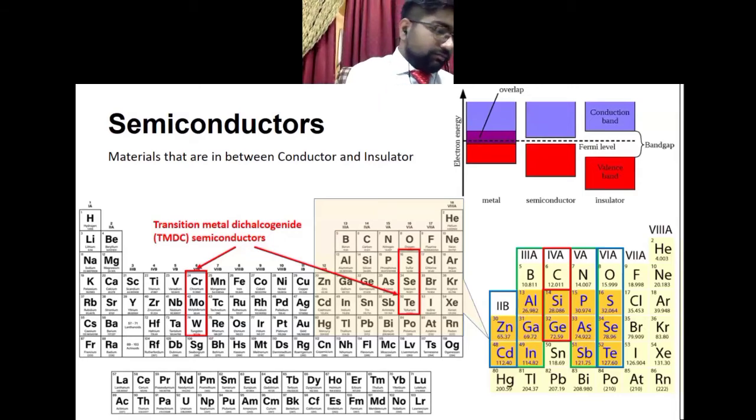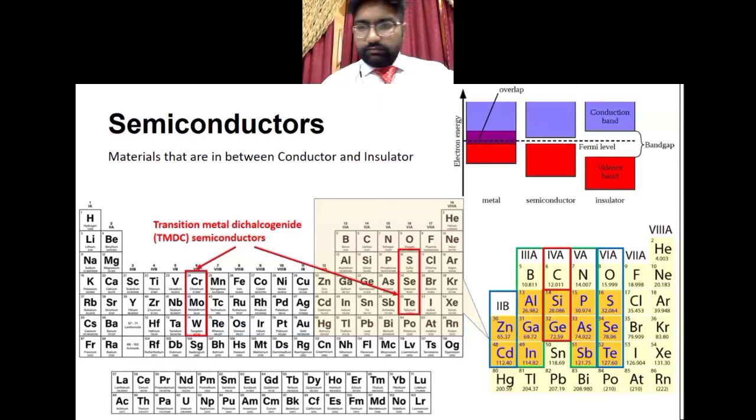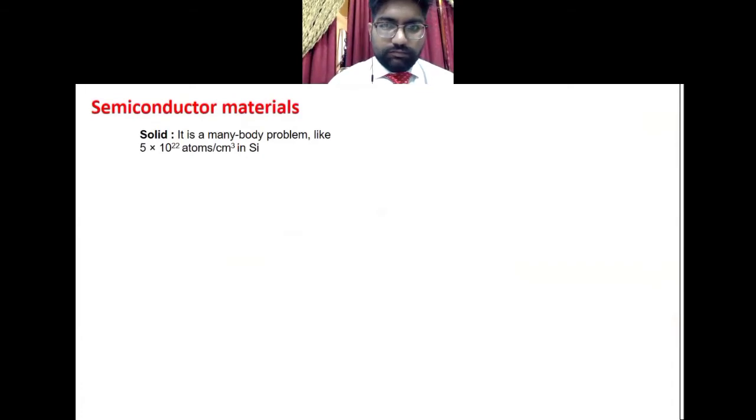And since it is very, very thin, the functionality is that graphene can work as a metal, but it can also let light pass through. If you put a metal, it will not let the light pass through, so it would not be good for photodetection. But graphene is conducting as well as transparent, and it also gives you a barrier. Using this barrier, you can separate out the electrons and holes, and that will give you a very good photo responsivity.